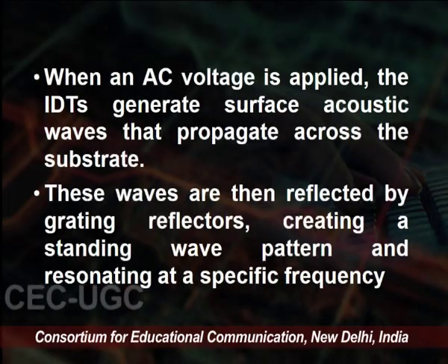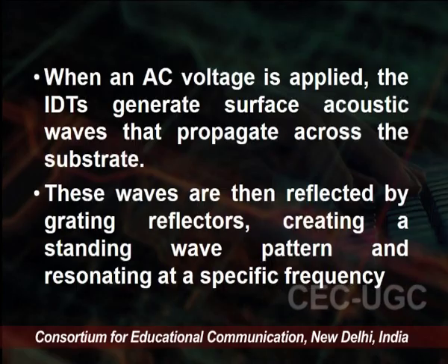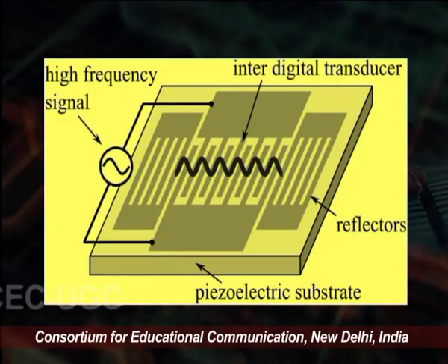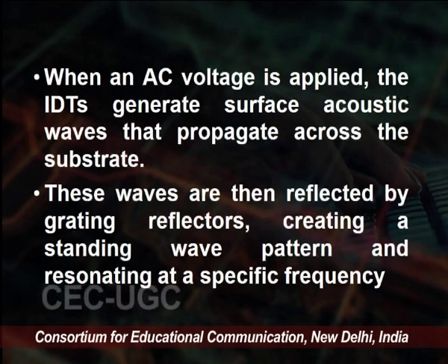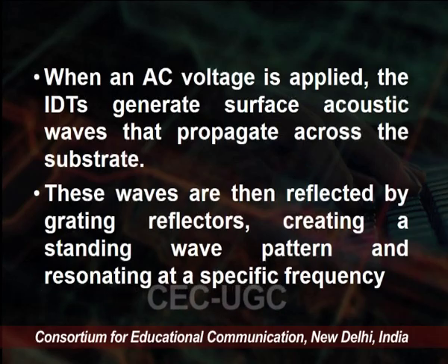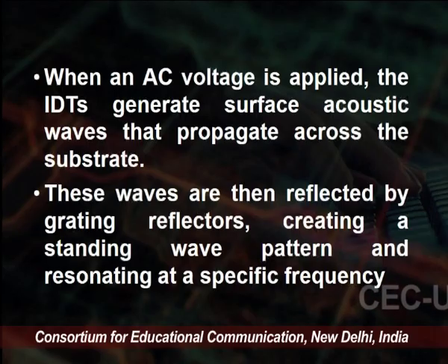When an AC voltage is applied, the IDTs generate the surface acoustic wave that propagates across the substrate. That we have seen here, that they generate the waves and that propagates through the surface. That is why it is a surface acoustic resonator, and these waves are then reflected by the grating reflectors, creating a standing wave pattern and resonating at a specific frequency.